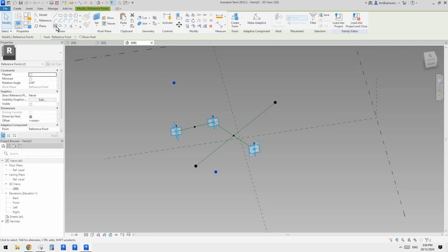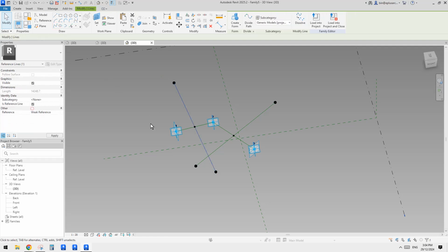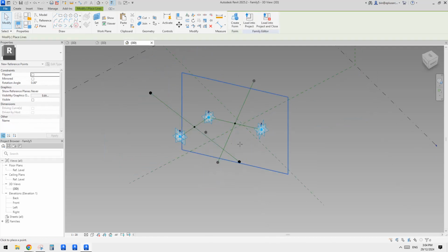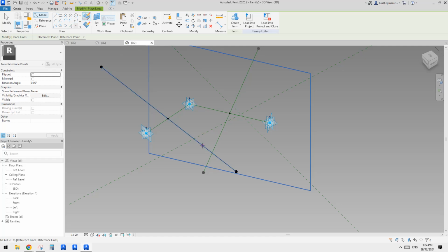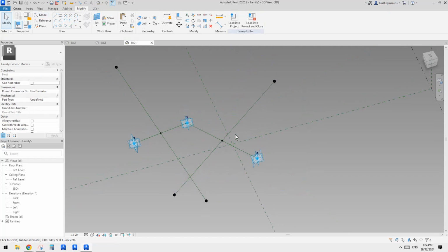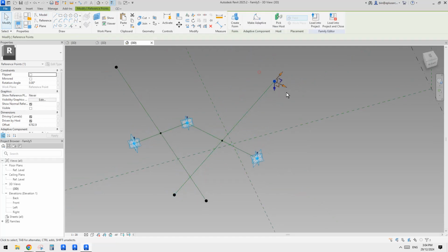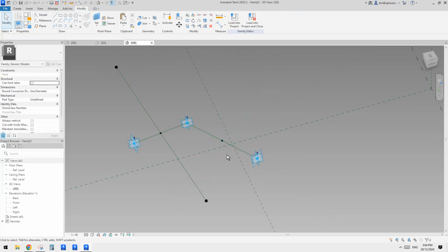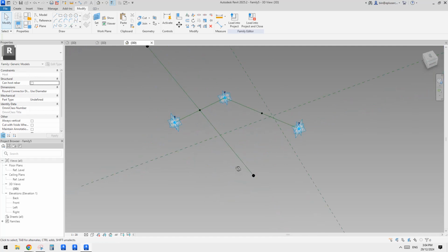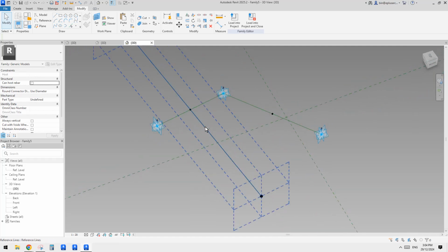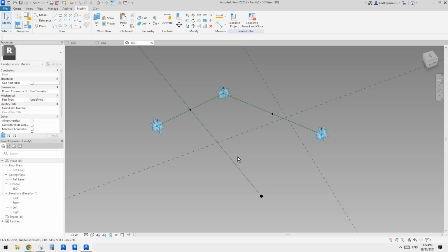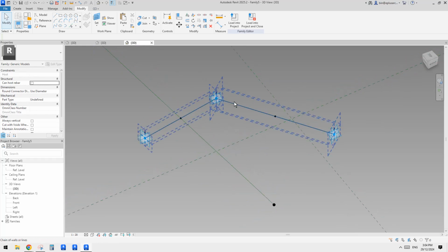Select these 2, create a spline through points, make it reference line. So now we can place a point to use draw on face onto this. Hang on, let me think. We only need one, I remember we don't need two. Yes, we can do that, place a point and intersect with that reference line, but we can also intersect